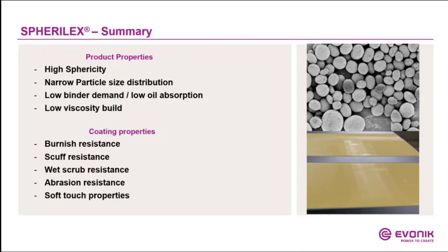For your coating, this means you can improve the burnish resistance as well as the scuff resistance. We saw that you can also improve the wet scrub resistance, which is very important for architectural coatings. Abrasion resistance could be improved, and due to the very special shape of the particles, so the sphericity of the particles, you can also achieve soft touch properties on the surface.